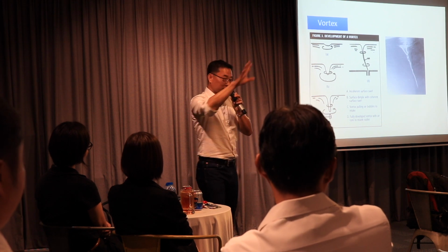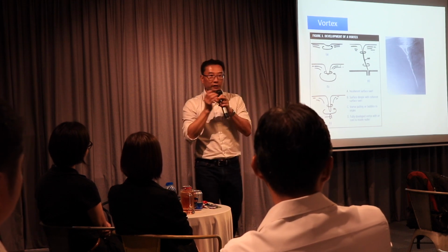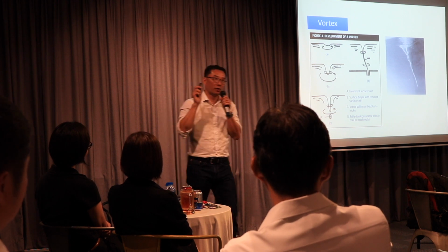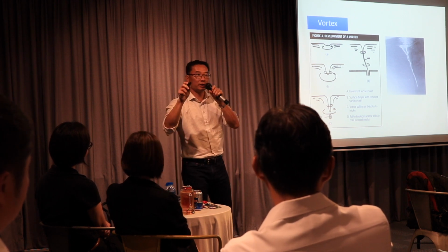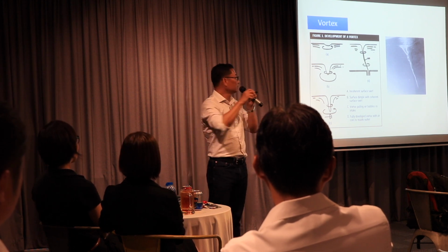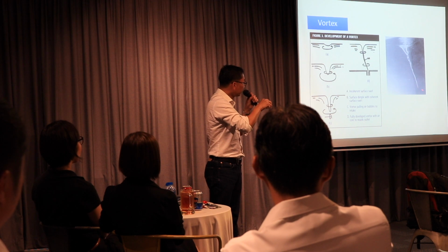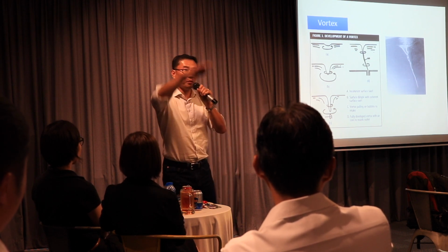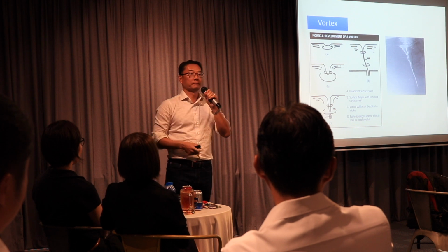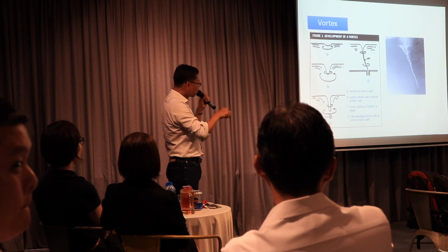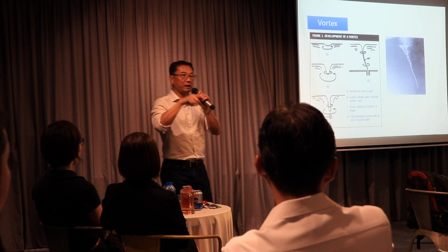Okay. But come to vortex. What vortex does for you, especially for a fire pump or for any tank contractor, is you suck air into the pump. Why? Because here is all air. So that's why you have a minimum submersion or minimum depth for the inlet pipe. So for this, vortexing will draw in air, and air is bad for a pump.